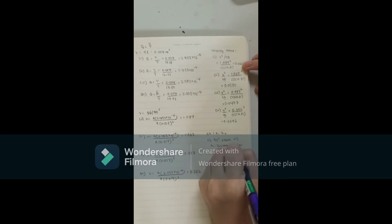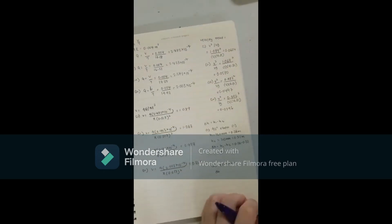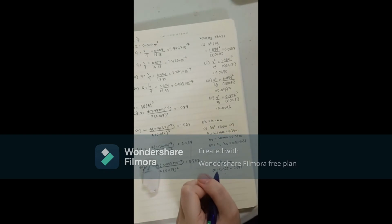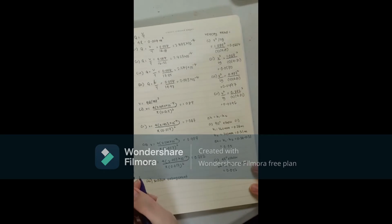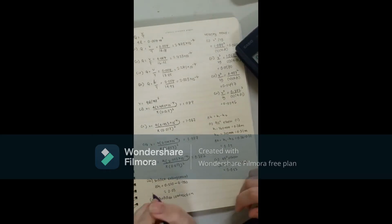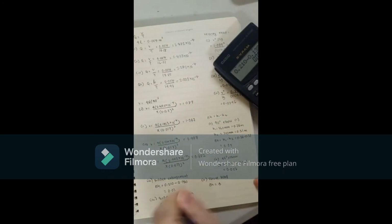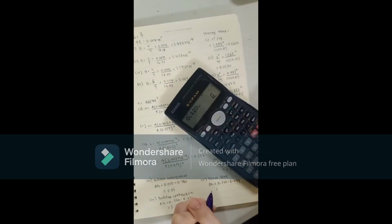Next one, I'm calculating the difference in piezometer head. For data 90 degrees elbow, the formula to calculate is H1 minus H2, where I get to change the unit in the table, because the unit in the table is millimeters, so I change to meters. I did it for 45 degrees elbow, short bend, sudden enlargement, sudden contraction, and 90 degrees elbow number 2.